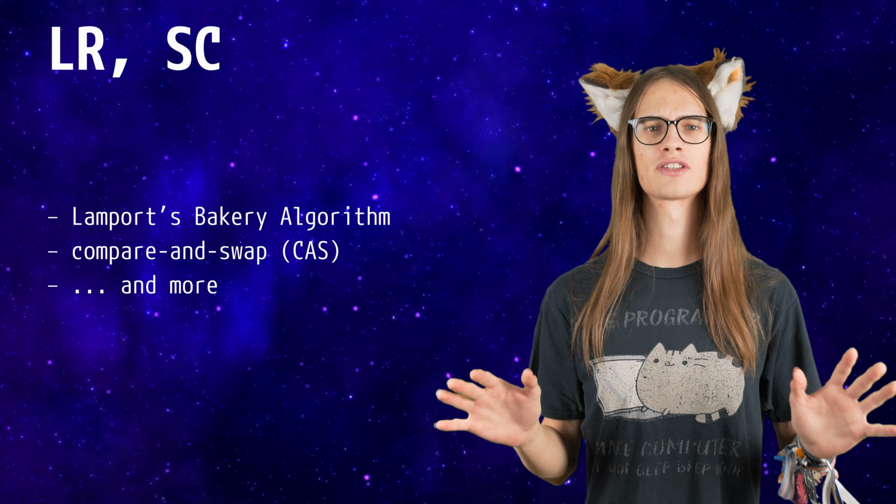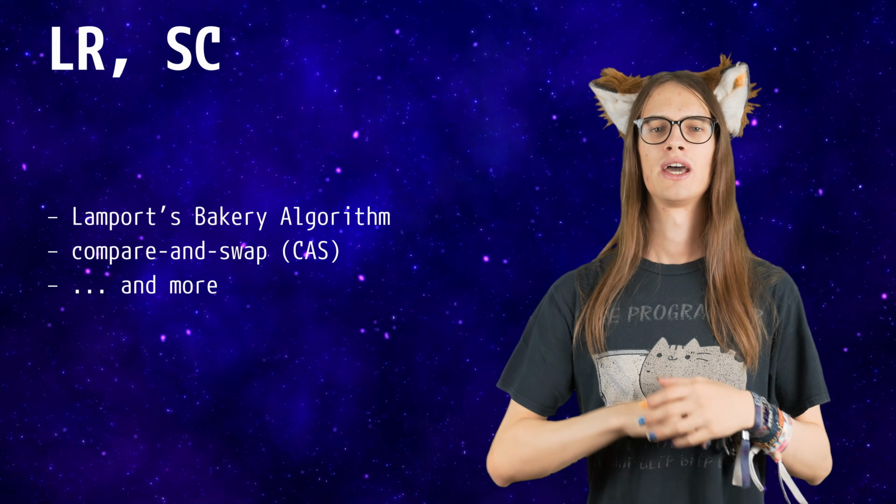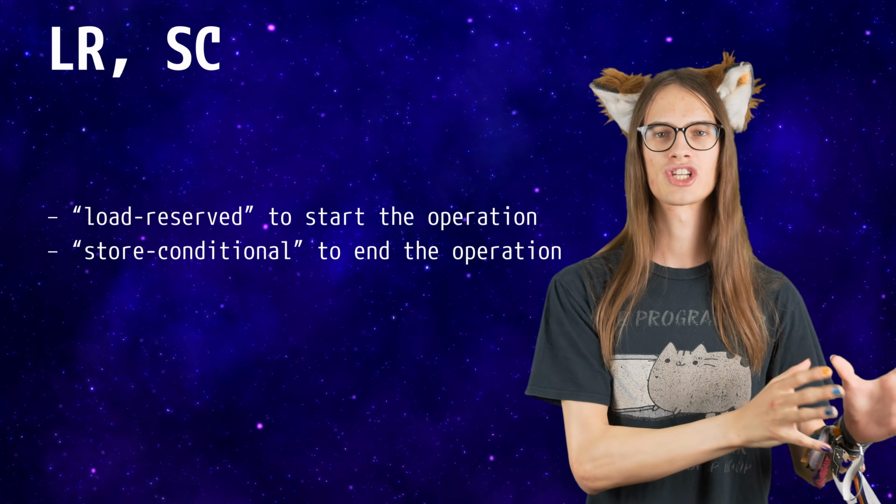Did you think that memory models would not come back to haunt us again? Funny. Let's talk about atomic operations, operations suited to multiprocessor synchronization. So, sometimes we have simple atomic operations, just the read, modify, write without being interrupted. However, those are really not suited for more complex operations where we need more than just a single atomic to ensure processes are synchronized. There are many different solutions for this problem, and RISC-V chose one that I think is somewhat unique while still turning out incredibly useful: the load reserved and store conditional pair.